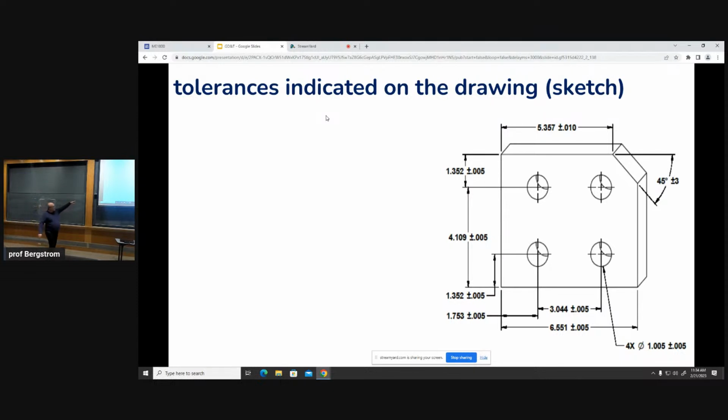Because those two fives add together or subtract together. Okay, once we made those two sides parallel, what's next? Now I think it's where we get our skinny vise. Now we can put it in the skinny vise because we've got two parallel sides, and we can make those dimensions, whatever it is.